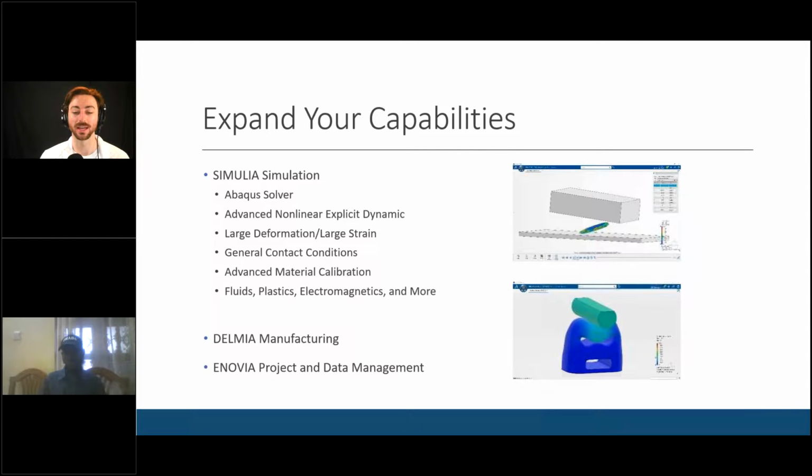If you're familiar with the Abaqus solver, it's an extremely well-known and powerful solver when it comes to FEA. You can carry out advanced non-linear explicit dynamics, like that can crushing animation up top, where you have much more deformation than would typically be possible within SOLIDWORKS. And that leads into the next step there, large deformation, large strain.